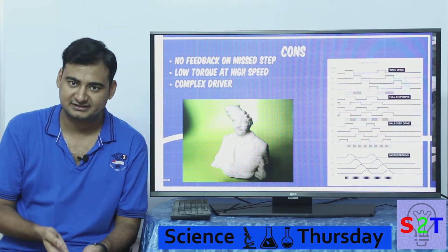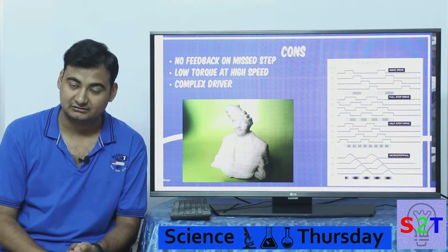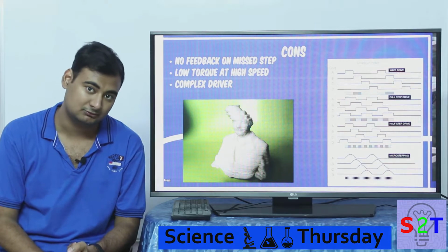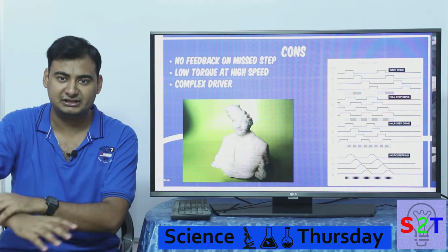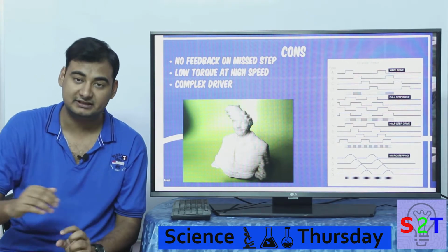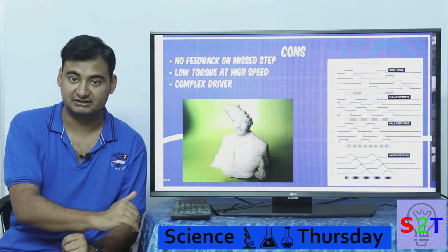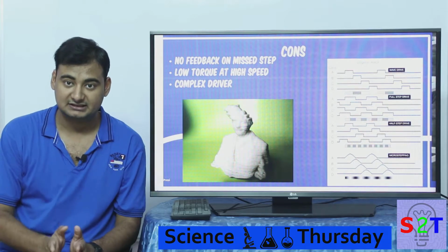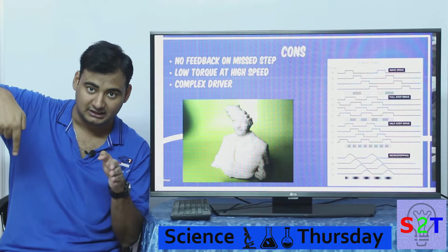At 10 rpm it has the same torque, at 50 rpm it has the same. However, this is very crucial with stepper motors. They lose torque if you rotate them very fast. So let's say you have a CNC bed that is very long, and the motor has to go along, it has to go very slowly, otherwise it will simply lose its step, and it has to overdrive because there is a lack of torque.